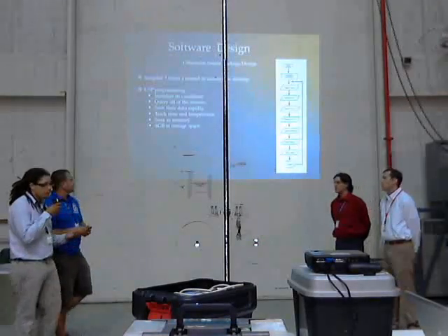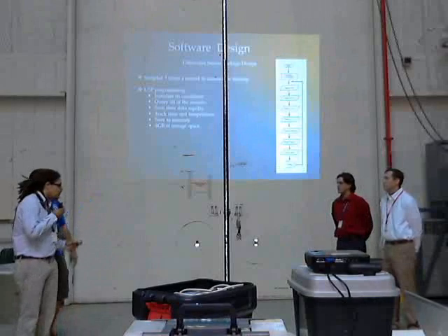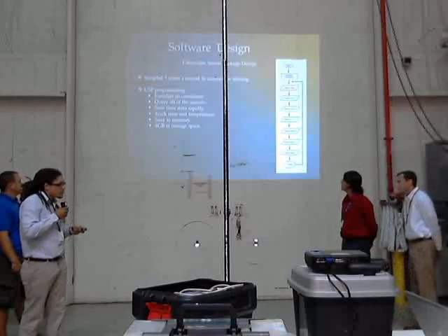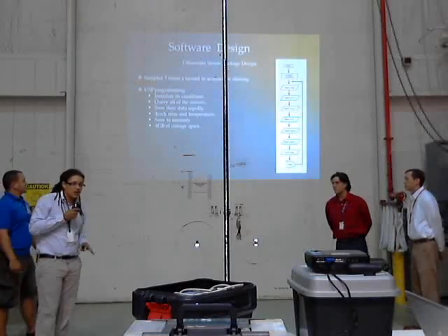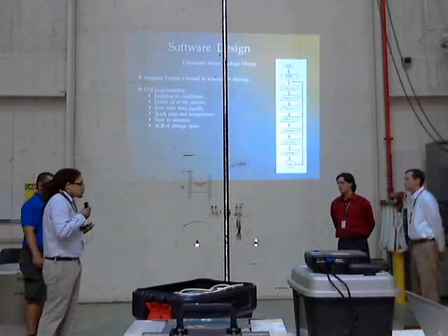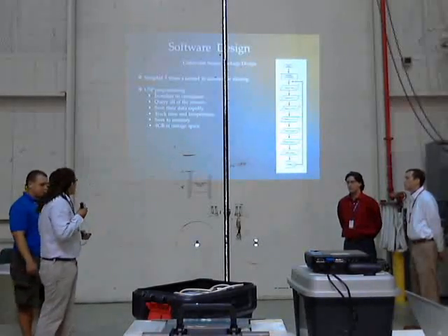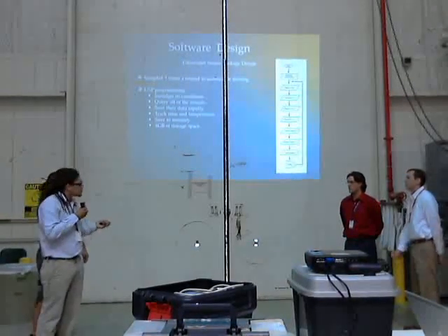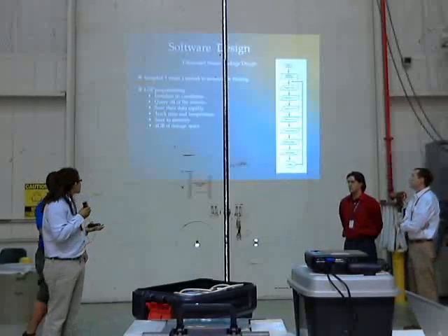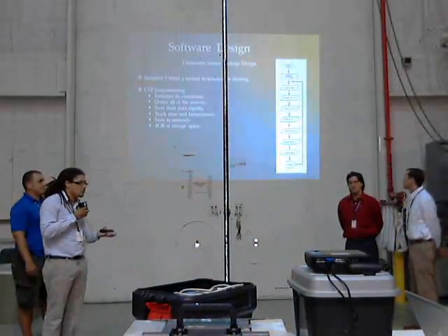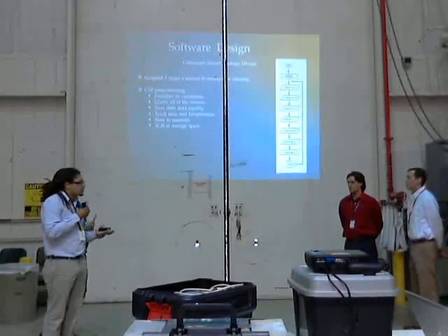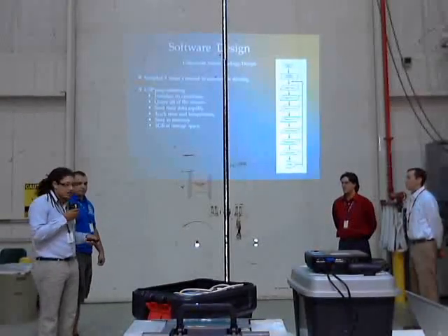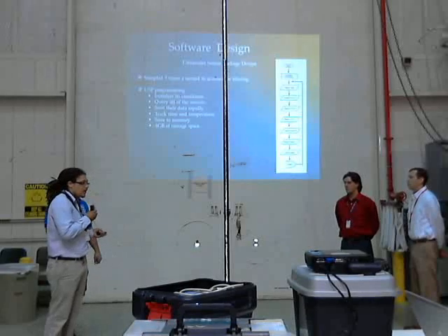The software for the UV project is as follows. Basically, we sample 5 times a second. We use the high rate of sampling to account for the spin of the box and other ways that the data can be corrupted. The code initializes the conditions, polls each sensor, and saves the data every 200 milliseconds. And then we track the internal and external temperature and save it to a 4 gig SD card, so that we don't have to worry about filling our memory up.